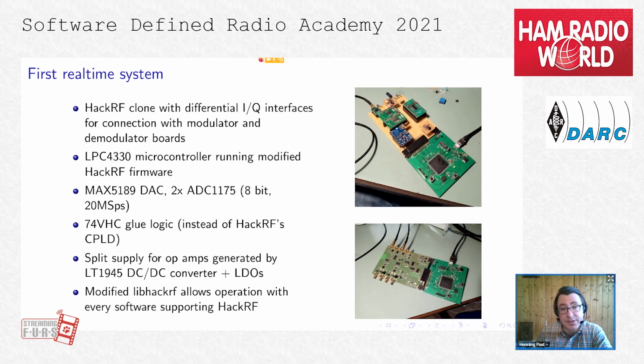The analog part used a dual rail design. This is why I used the DC-DC converter, which converted the 4.5 volts you effectively get from the USB to plus 5.5 and minus 5.5 volts, and then I placed an LDO in each rail to generate clean plus minus 5 volts for the analog part, with proper filtering, of course, because DC-DC converters are a bit problematic.